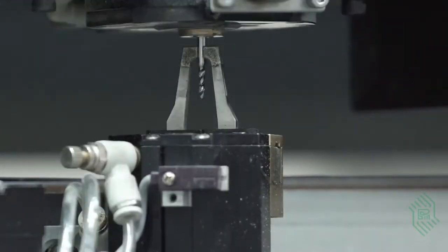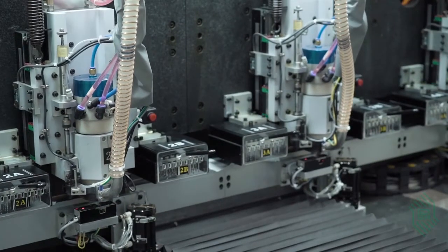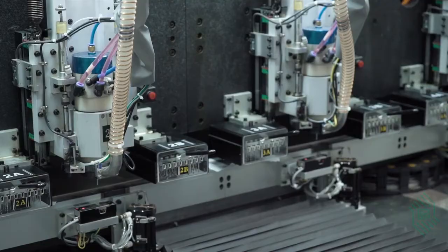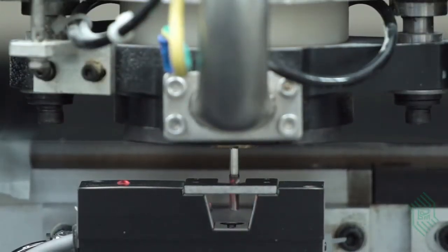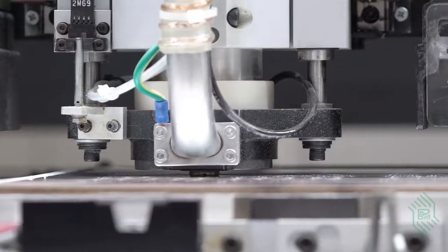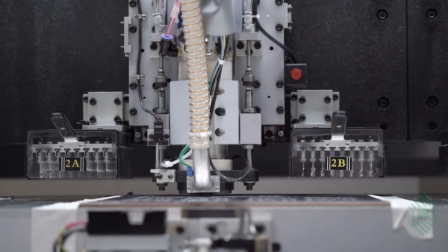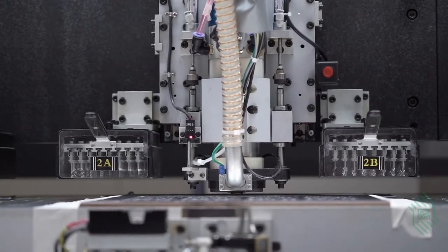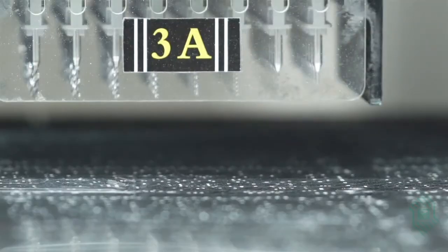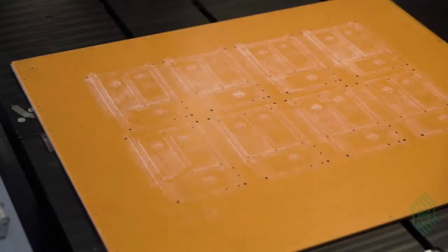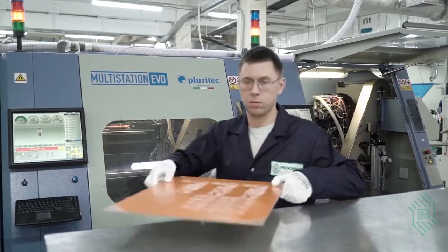The machine selects a tool from a storage magazine, checks the length, diameter, and beat with the help of a laser measurement station. The contact drilling system ensures drilling with depth control, which is necessary for making blind holes in HDI multilayer PCBs. The panels are transferred to the next operation, the choice of which is made according to the flowchart of the particular PCB type.